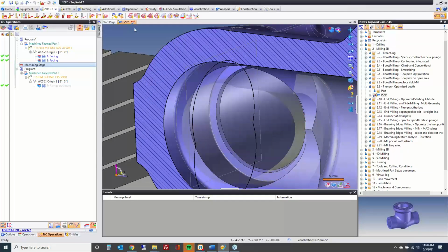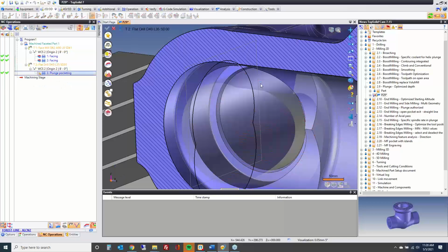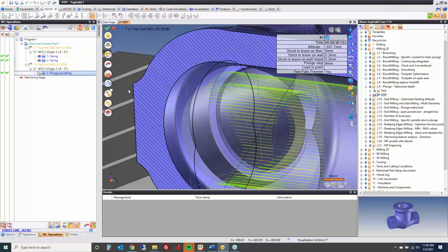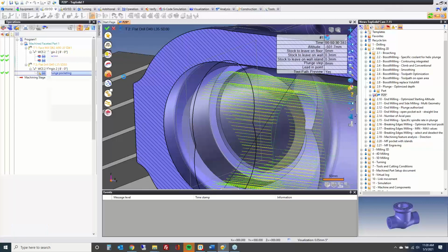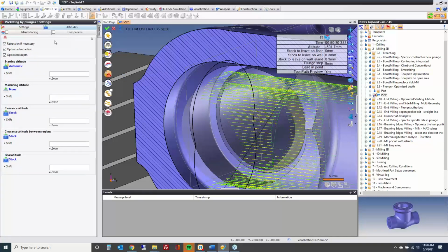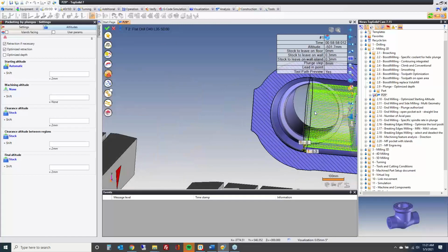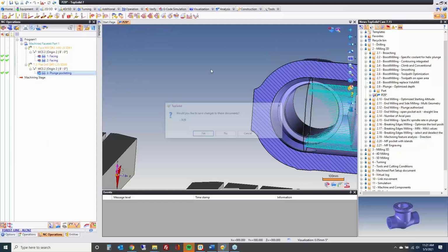So with that said, if we look at this new option, we go into our settings and we go to altitudes. If I turn this off, you'll see the difference right here on the left side of the toolpath, because now it's drilling unnecessarily, right? Or to depths that are not necessary. If we activate this, it's really paying attention to the updated stock model. Okay. Perfect.